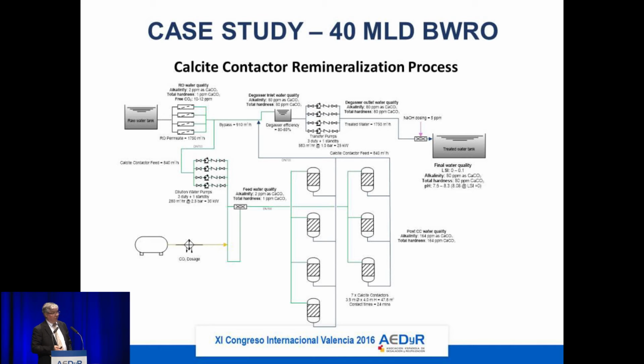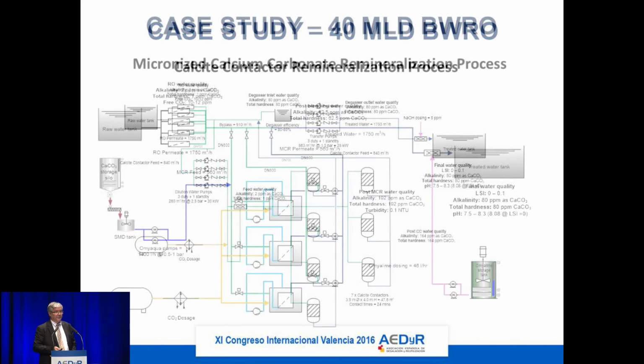A little case study here, just to go through that, using a calcite contactor. You have a lot of equipment and capex cost, like with pumps. You need to pump that through these calcite contactors. Then at the end, you go to a degasser. After the degasser, you need to pump it again to a storage facility.